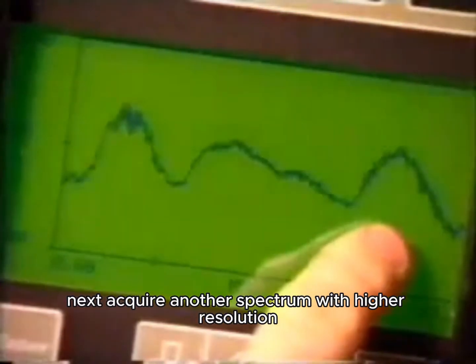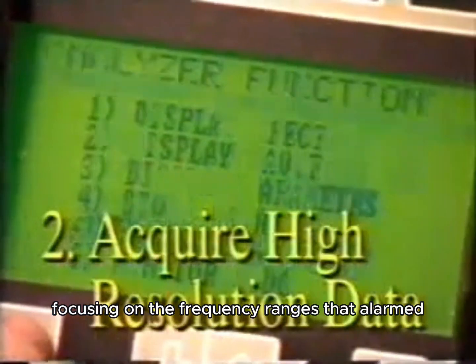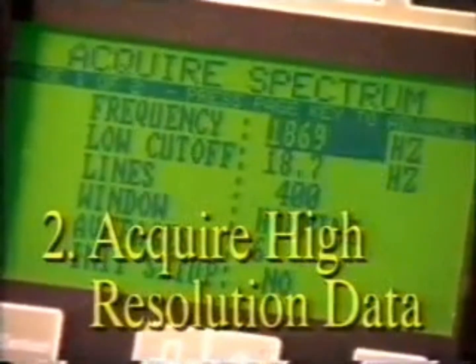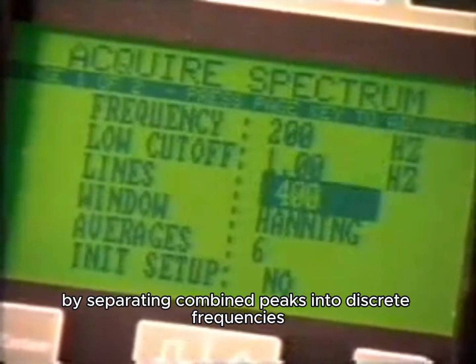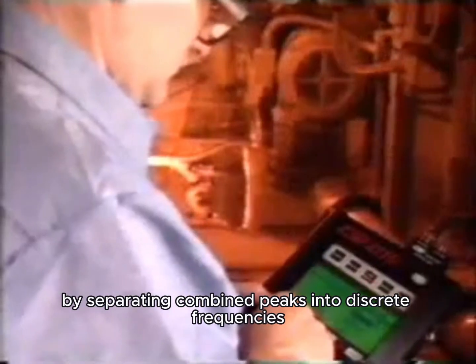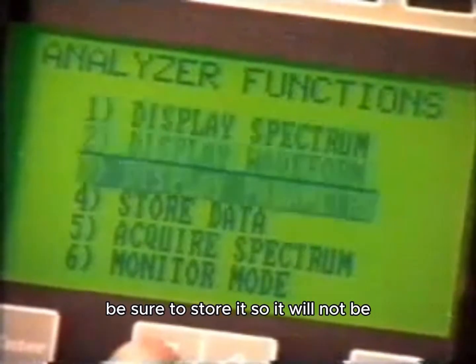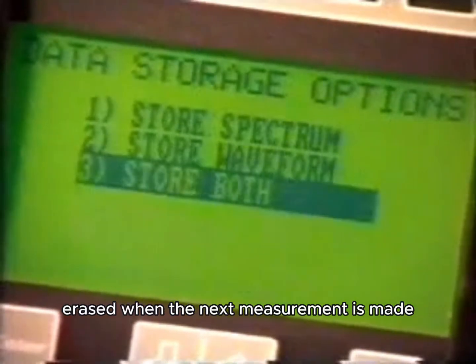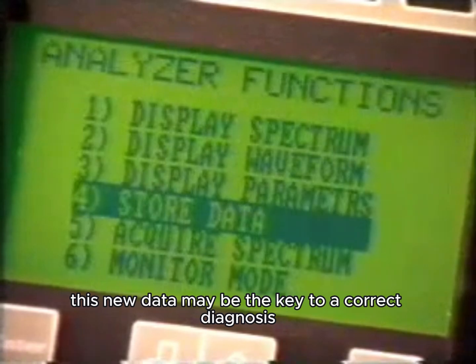Next, acquire another spectrum with higher resolution and perhaps focusing on the frequency ranges that alarmed. This high resolution will help pinpoint the source of the problems by separating combined peaks into discrete frequencies. After viewing this new data, be sure to store it so it will not be erased when the next measurement is made. This new data may be the key to a correct diagnosis.